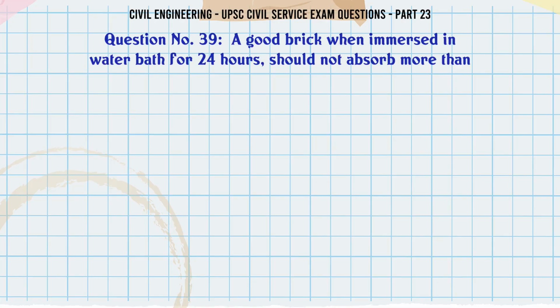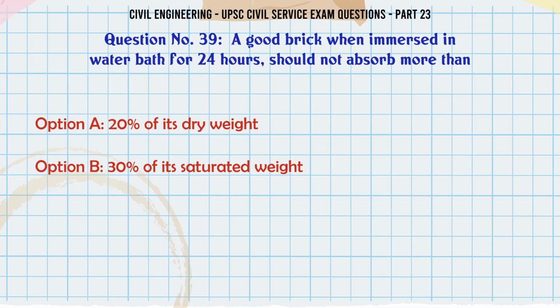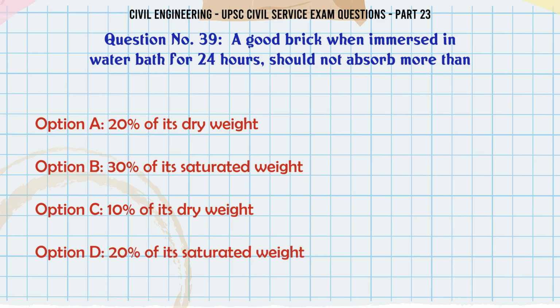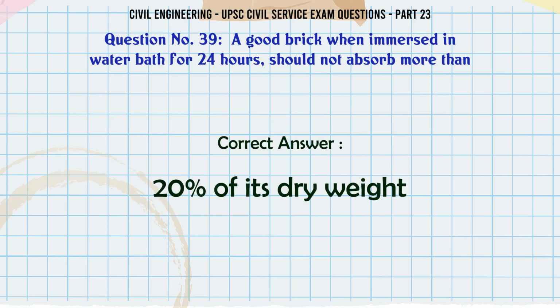A good brick when immersed in water bath for 24 hours should not absorb more than A. 20% of its dry weight, B. 30% of its saturated weight, C. 10% of its dry weight, D. 20% of its saturated weight. The correct answer is 20% of its dry weight.